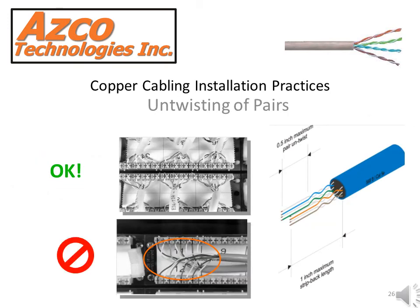When terminating the cable, it's necessary to untwist the twisted pairs of the conductors somewhat in order to fit them into the IDC terminations or into baluns or other such devices. It is recommended that you never untwist more than half of an inch. The more untwisting that is done, the more noise will be created in the cable, therefore degrading the performance of the cable.